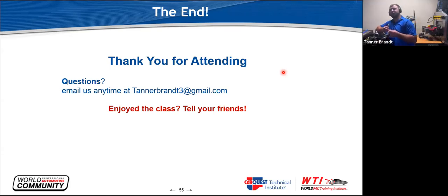They're serving the same purpose. So they all serve the same purpose of they don't want turbo surge, because what happens with turbo surge is now you're building a lot of boost, and maybe that boost isn't going to be used. So turbo surge is typically pretty loud, also makes the vehicle run funny, and then isn't good for the turbo because it's essentially going to spike the boost pressure, or can spike the boost pressure, which isn't good for anything. So yeah, all serving the same purposes, just to, well, noise and longevity of turbos.